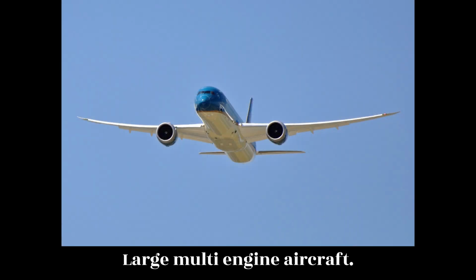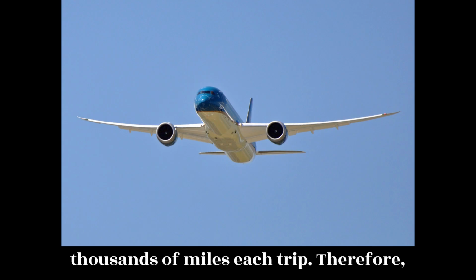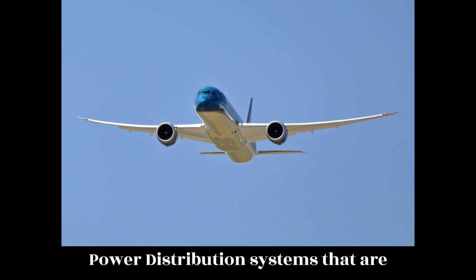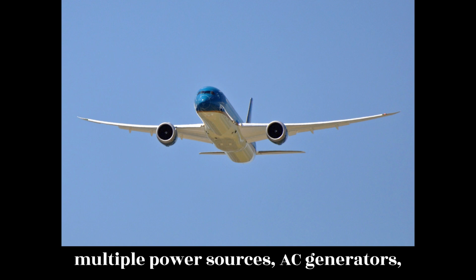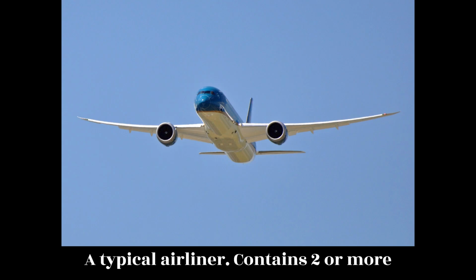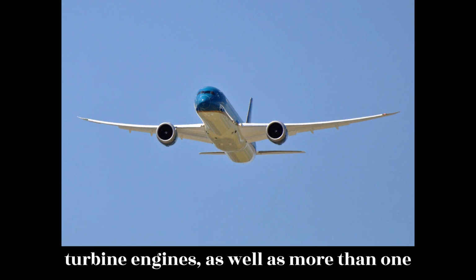Large multi-engine aircraft. Transport category aircraft typically carry hundreds of passengers and fly thousands of miles each trip. Therefore, large aircraft require extremely reliable power distribution systems that are computer-controlled. These aircraft have multiple power sources, AC generators, and a variety of distribution buses. A typical airliner contains two or more main AC generators driven by the aircraft turbine engines, as well as more than one backup AC generator.